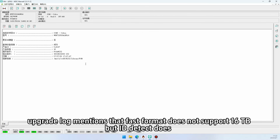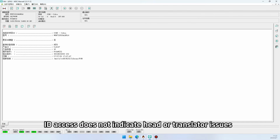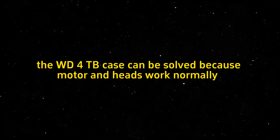The upgrade log mentions that fast format does not support 16 TB, but ID Detect does. Note this is only a PCB without the drive, yet ID info can be obtained. ID access does not indicate head or translator issues. Combined with this, we explain here. The WD4TB case can be solved because motor and heads work normally.